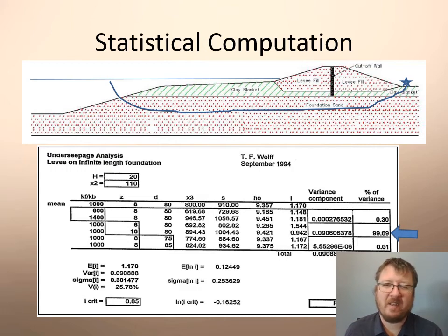This doesn't necessarily mean that the levee fails. First, there might be other nodes: the water has to come up to 20, so there's a certain probability of that. Then there might be an intermediate node for whether the water is there long enough to initiate the seepage failure mode, since there might be some chance that the water is only there for a short duration. Finally, the erosion has to cause piping, and the piping has to progress long enough that it collapses the levee. That might take some time after the factor of safety less than 1 is realized for the levee actually to fail. So that illustrates how some heavy calculations are just part of the full picture of how the levee might fail.